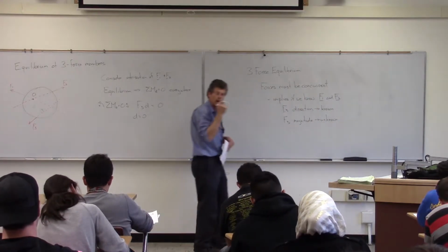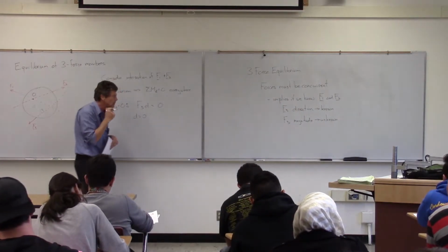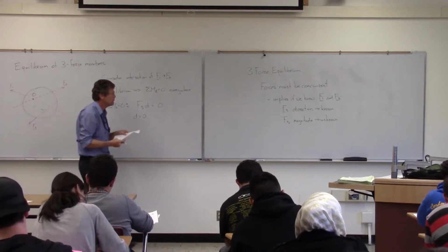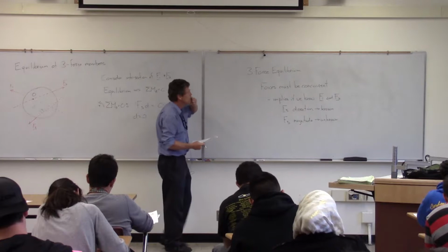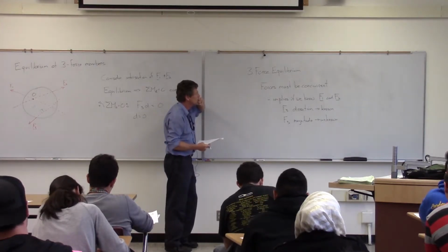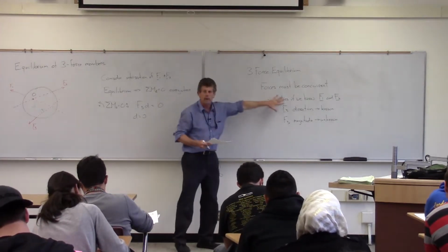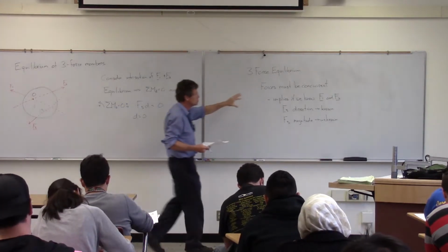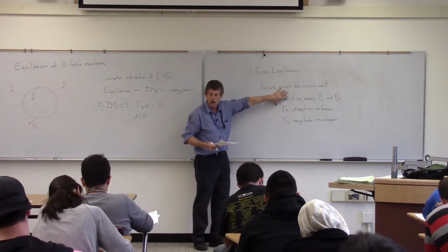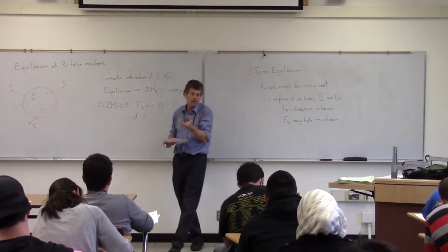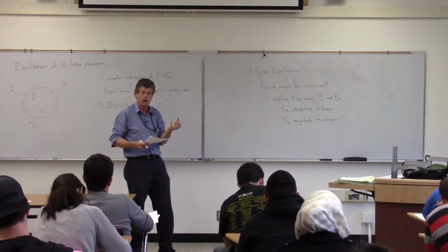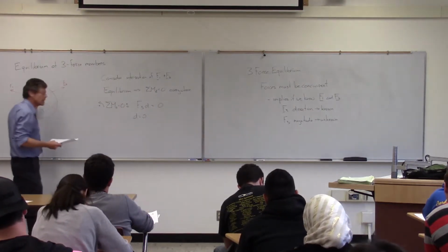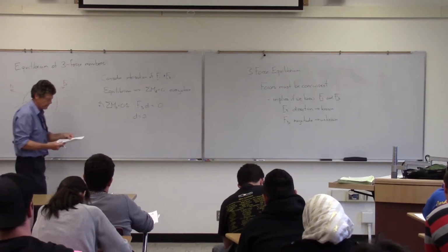But I can solve for that by putting it into equilibrium, setting the other side equal to 0. Now we have to be a little careful because, going back to the special equilibrium case, since those are concurrent, we're only going to have Fx and Fy, sum of forces in the x direction and the y direction, available to us. The moment equation's not going to help me in this particular case because they all go through the same point.